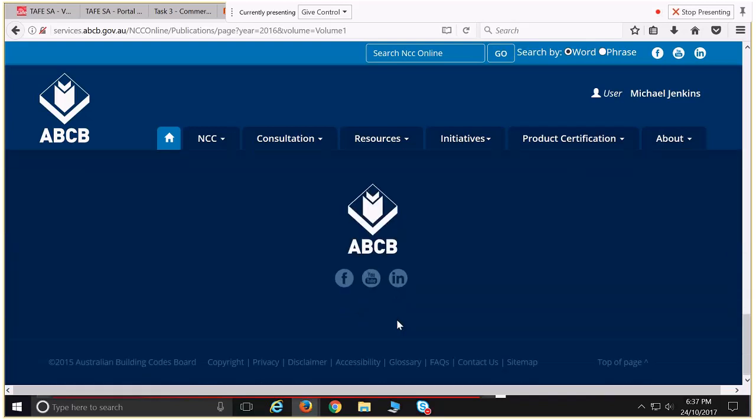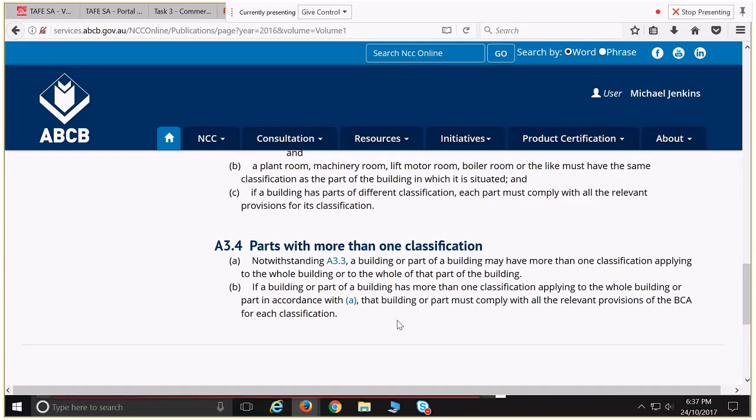What I was hoping to get to was possibly it's in fire resistance under that. It says, so when we go for attributing fire rating levels to all the walls, for buildings with multiple classifications, you must adopt the more stringent of the fire ratings of any of those classifications. So we've got 5 and we've got 6, and we have to adopt the more stringent of those classifications, which by the way will be number 6.